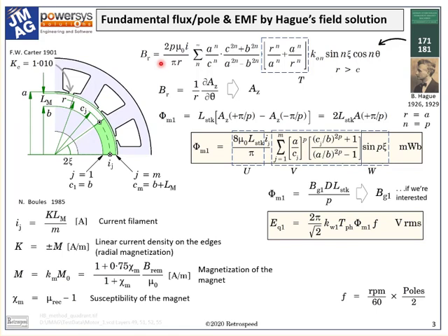And what we're looking at is a solution of Laplace's equation in the air gap and Poisson's equation in the magnetized region of the magnet, expanded in an infinite series of harmonics, n from 1 to infinity. Note that n is the order of the mechanical harmonic, not the electrical harmonic, so it includes all harmonics and not just the electrically interesting ones. In our case, however, we are going to pick out the working harmonic, which corresponds to P equals 5 pole pairs, so n equals 5, and this is the first or fundamental electrical harmonic.